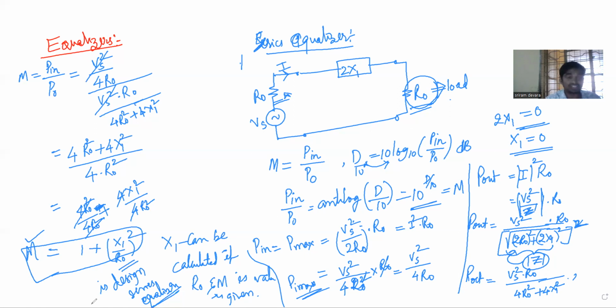Because due to a distorted signal there is a possibility of some loss. So to avoid this loss, we have to place equalizers. Equalizers provide a uniform response over the entire frequency range. So therefore, equalizers are very essential for a communication circuit. Therefore, we can avoid attenuation distortion, phase distortion, and all.